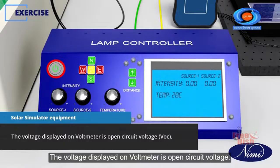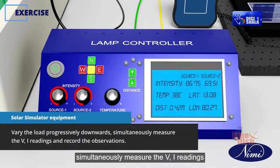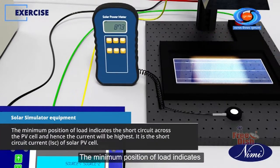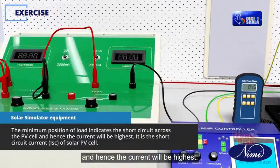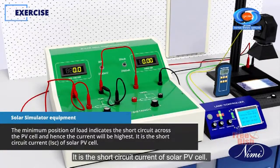The voltage displayed on the voltmeter is the open circuit voltage. Vary the load progressively downwards. Simultaneously measure the VI readings and record the observations. The minimum position of the load indicates the short circuit across the PV cell, and hence the current will be highest. It is the short circuit current of the solar PV cell.